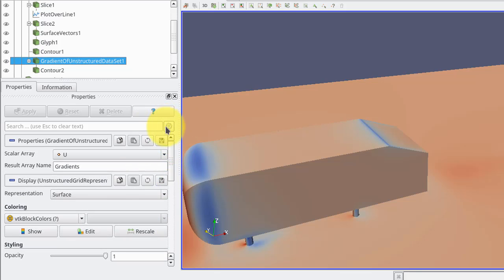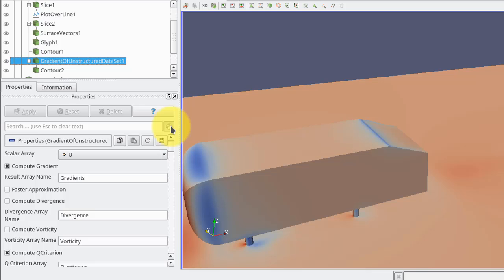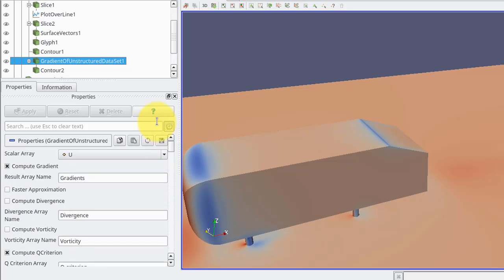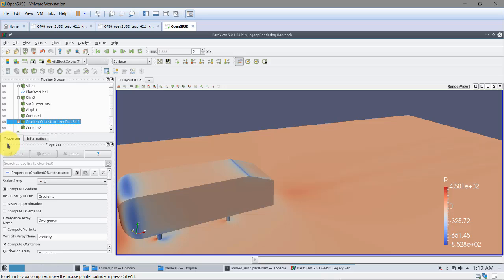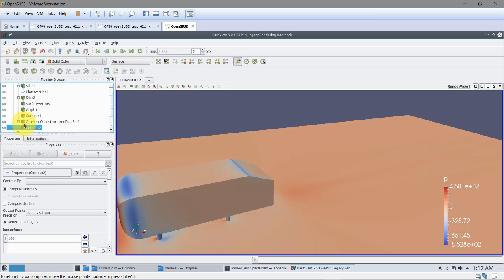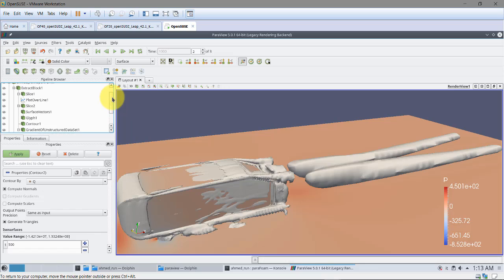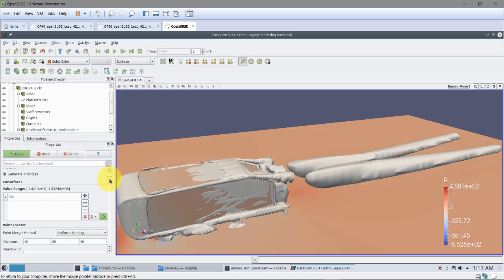To access that information, you can enable advanced features here. So remember this button, always click here and you get more features. See here that we have access to all those features. So we have here compute vorticity, Q criterion. You just come here and you can get those quantities. And as soon as you have the Q criterion, again like we did with the previous solution, just plot surfaces, contours, okay, and then choose a value for that quantity. Usually Q criterion is a positive quantity, okay. You need to play around, but usually go and choose a positive value of about 100.